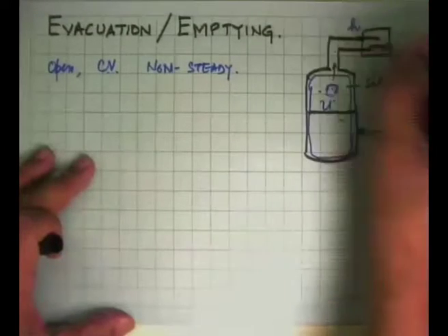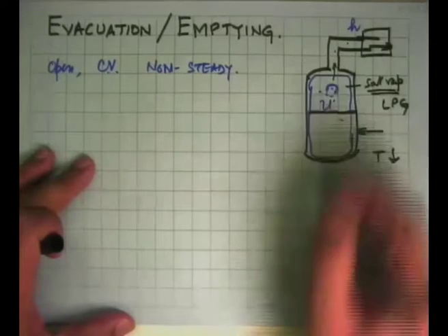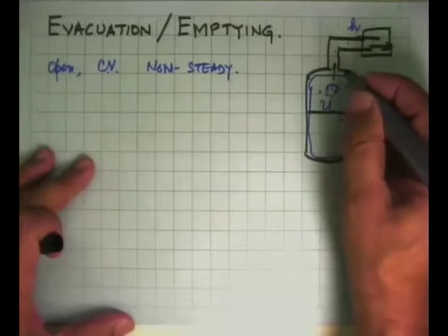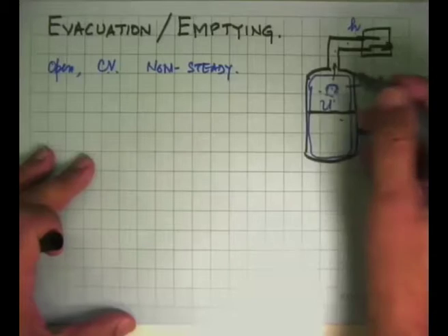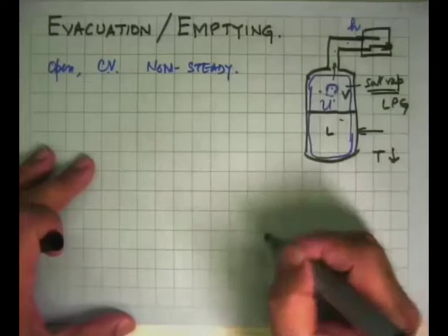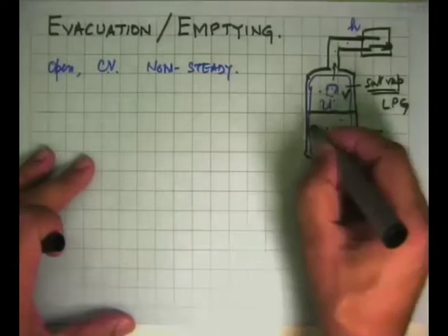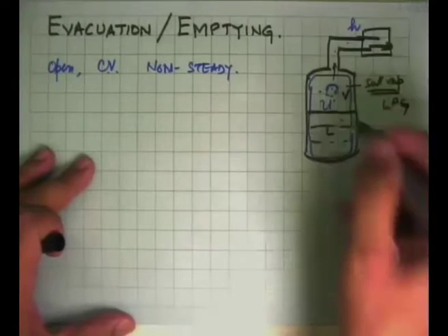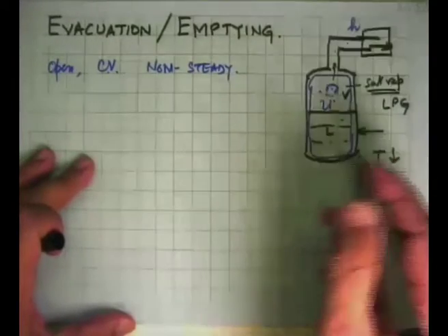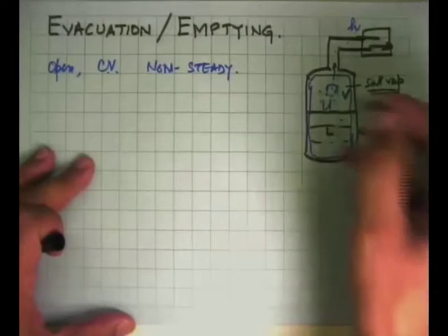So we are drawing off saturated vapor, dry saturated vapor, even though in the cylinder as a whole, we had a wet state. There is liquid there, there is vapor over there. And as we keep drawing out, the liquid level keeps going down. But if the temperature were constant, we always had the wet state at the same condition.